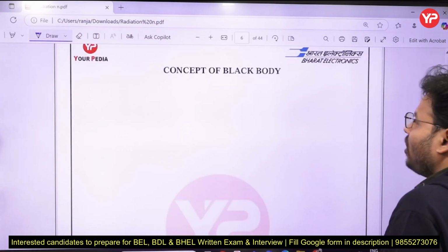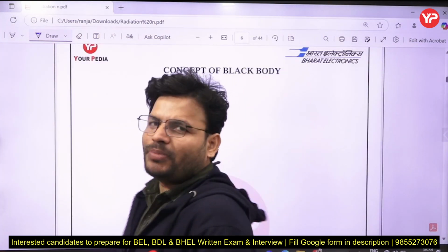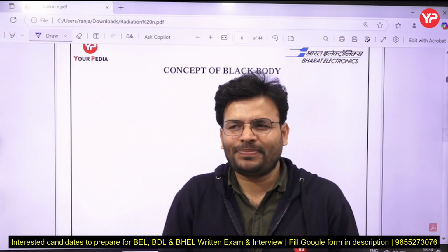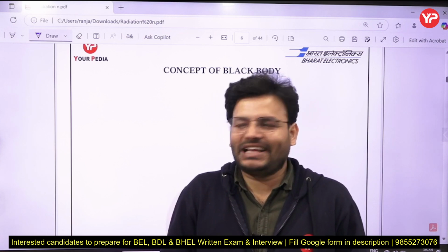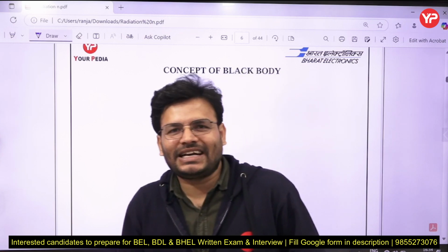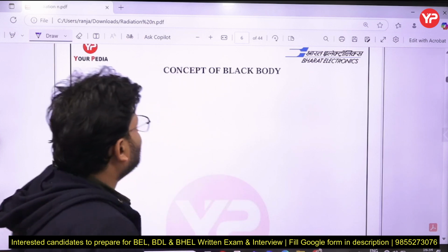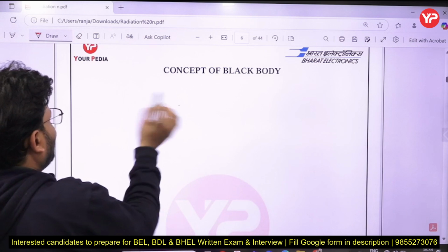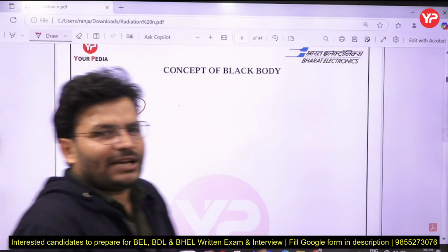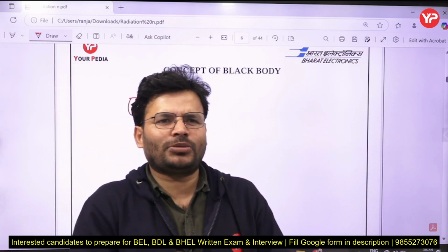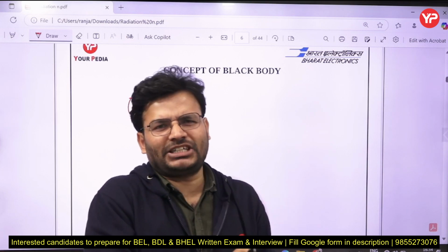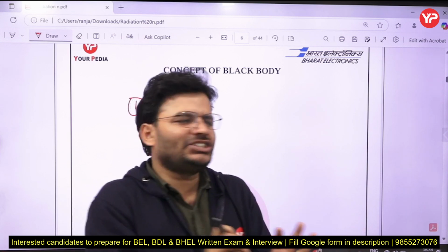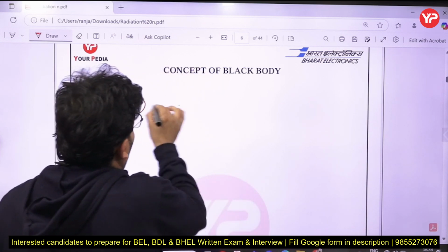Now I am going to discuss the concept of black body. What do you mean by black body? In the offline class, when I ask the students what is a black body, they think, sir, anything which looks black in color will be considered a black body. No, my dear friends, that is not a black body. Basically there are 2 or 3 important points that you have to keep in mind about the black body. First point, it can absorb all the incident radiation. It doesn't matter what the wavelength is, what the temperature is, whatever incident radiation is there, it can absorb all of it.